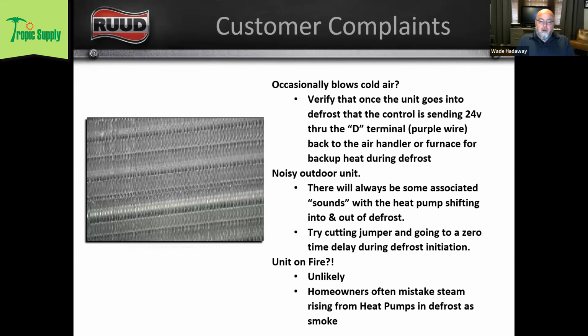And then another complaint that sometimes you'll hear, typically with people who've never had a heat pump before, is when the system goes into defrost, they hear a noise, they look out the window, and they see what they think is smoke rising from the outdoor unit, right? It's really just the steam from melting the frost that's on the coil, but sometimes people mistake that for fire, and they think that the unit's on fire. So just a couple things that you would want to talk to your customer about while you're talking to them about getting a heat pump.